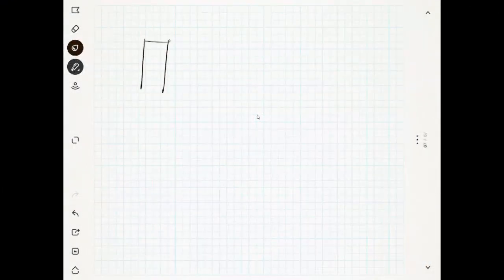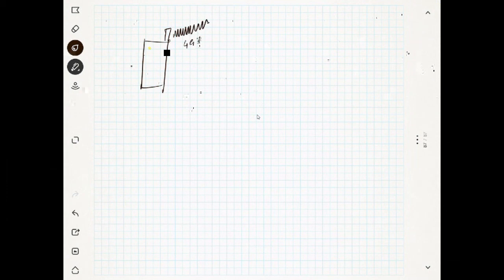So if you have a mobile phone, the carrier frequency coming from it is in gigahertz. But if you are speaking to your friend, the frequency which is coming from your mouth is actually 3.1 kilohertz. Then why are you using this much high frequency, 2 gigahertz? So the signal can reach the other person, I think, or the satellite.